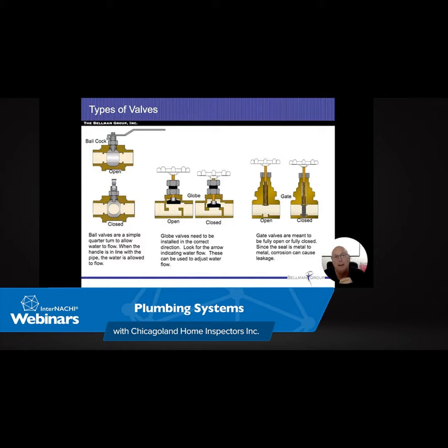All right, drain waste piping again. Let's move on. Proper pitch is important for good drainage. This is a test question. And I know one of our field houses that we had in the south suburbs, we were looking at waste lines that were going on almost a 45-degree angle. We had some of them that were going up as well. So the proper pitch is important. I do want you to know 1/4 inch per foot is the acceptable slope of this stuff.